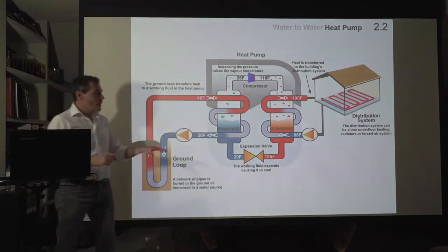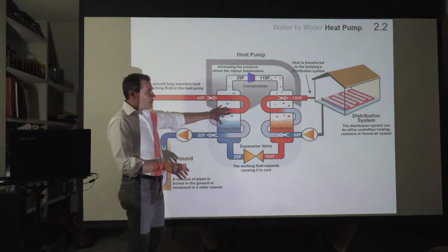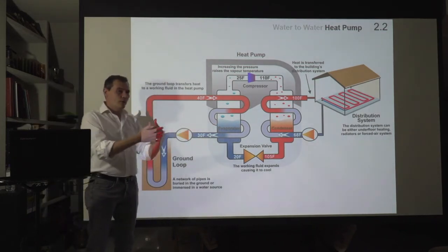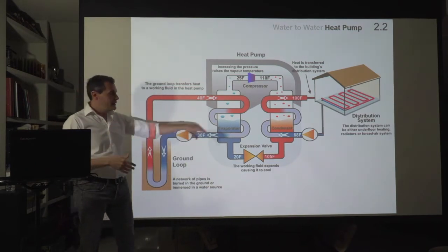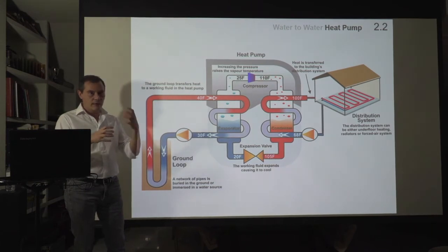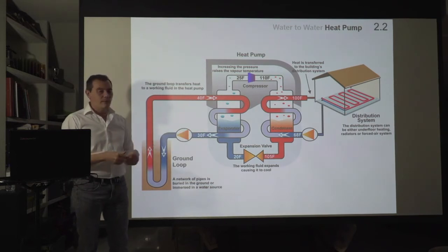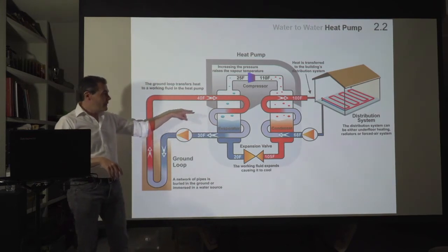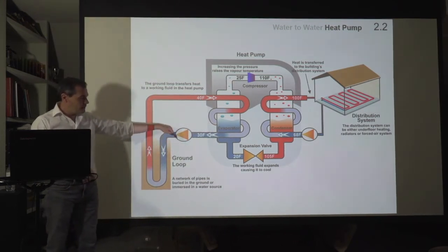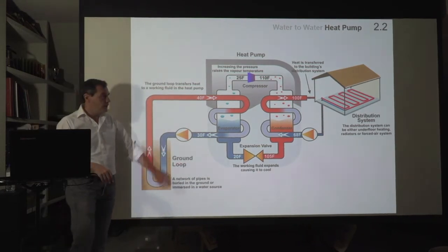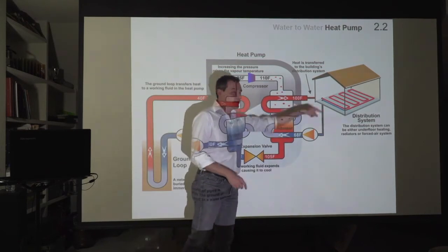And this is it. We have a device, we have a box. We don't need to split that system. So this is a heat pump, so we don't need an indoor unit and an outdoor unit. This is indoors. That's good because we don't have an ugly, noisy thing outside the building, on the roof or whatever. Those elements are not noisy, and we can have a mechanical room, and we can place that there. But then we need pipes. We need this. This is outdoors, and we need all these pipes buried in the ground. And then we need the radiant system inside the house.